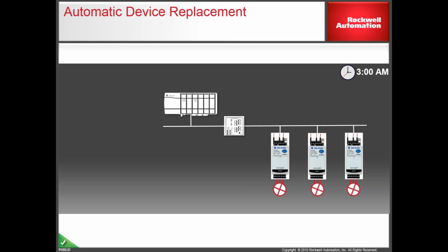But if I replace one, let's say I didn't replace the COM module, just the E300, then it would recognize that the configuration was different. The configuration data would stay the same because that's going to be housed in the control module. So the COM module, if it had the same IP address, when it establishes that connection, does a kind of handshake or open messaging, and then it'll sense any configuration mismatch and try to download it.